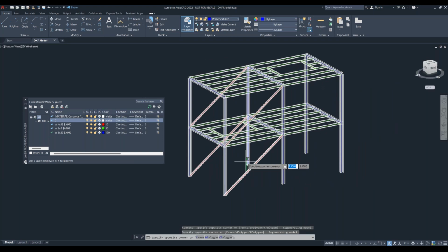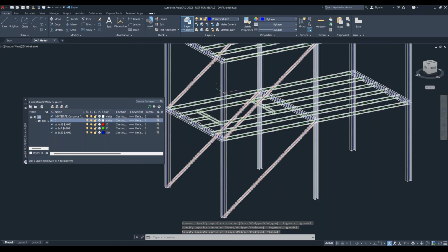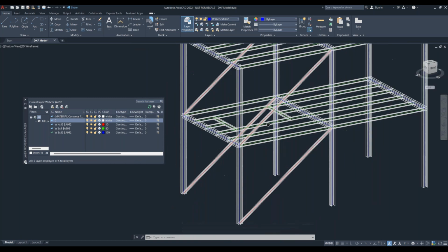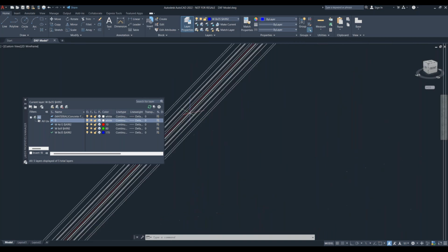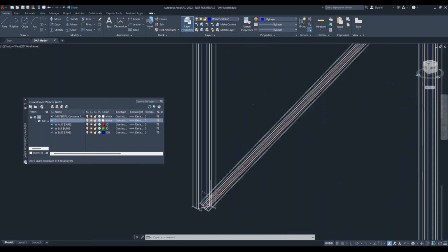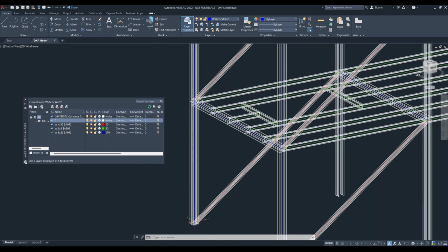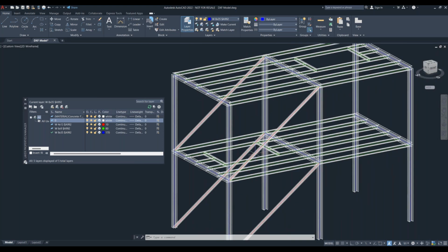You can see I have my member lines, the outlines of my members here. And then what I've done was drawn in the analytical lines at the center of all of my members here. And then depending on the cross section, I made multiple property layers for each cross section. So here my red lines are corresponding to my red layer. And those are my W 4 by 13s with the material here.